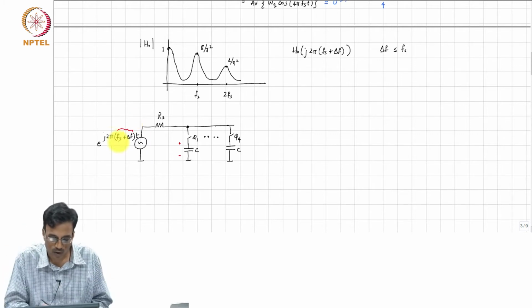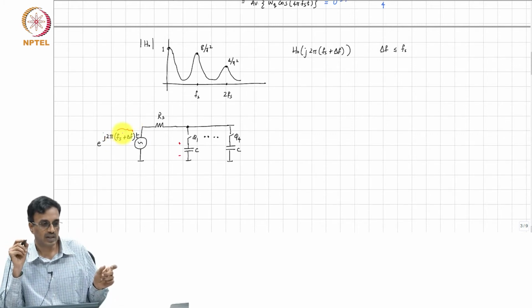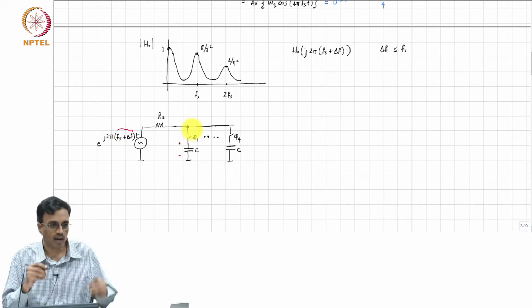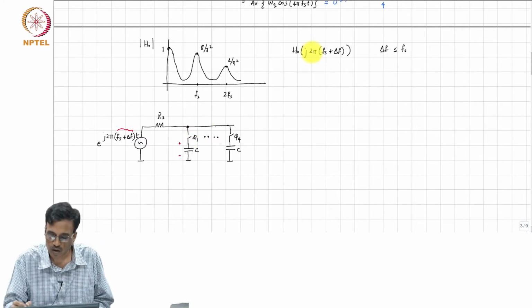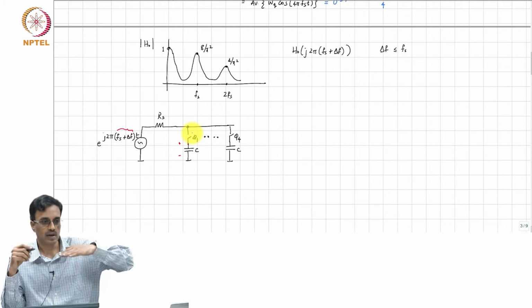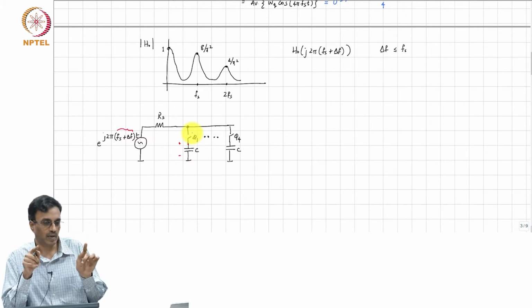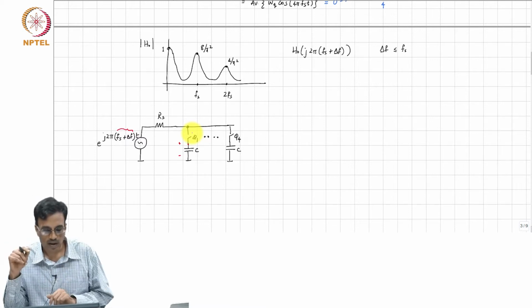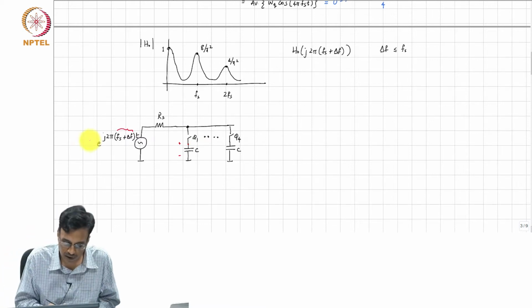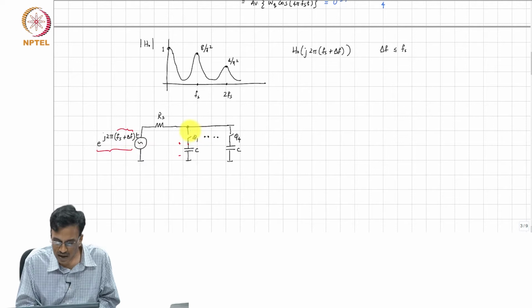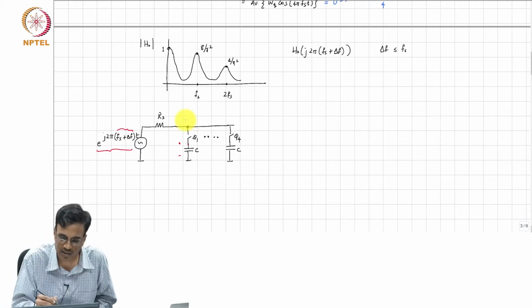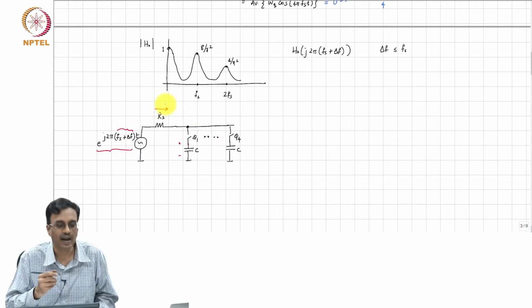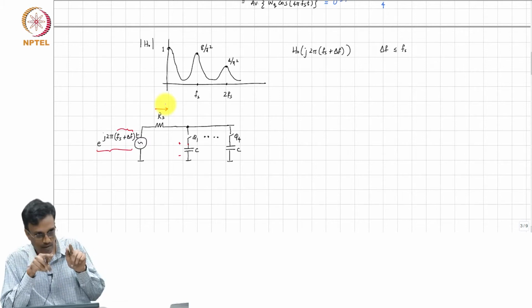Exactly, right. So, when the input was exactly at a frequency Fs, this voltage would remain constant from cycle to cycle, right. So, in steady state, in this cycle it would be some waveform, in the next cycle it would be exactly the same waveform, and intuitively that is because you can think of it as the following: this input frequency at Fs, right, is being switched at Fs. Switching is basically, in other words, this current, right, we are sampling or multiplying it with a square wave at Fs.